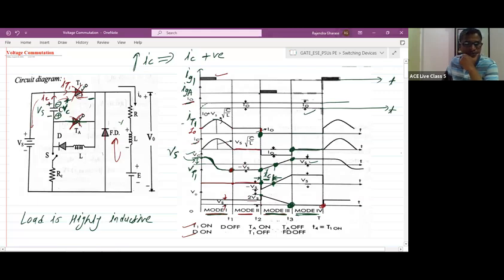And the important thing is, while selecting a device for any application or circuit, suppose my circuit gives a peak value of current through this switch of, let us consider, 100 ampere. Then I will not select a thyristor with a maximum current rating of 100 ampere. I will select a thyristor with a slightly higher current rating, in order to avoid the damage you mentioned.